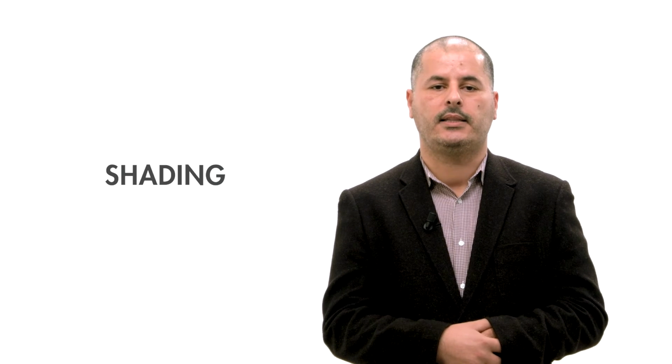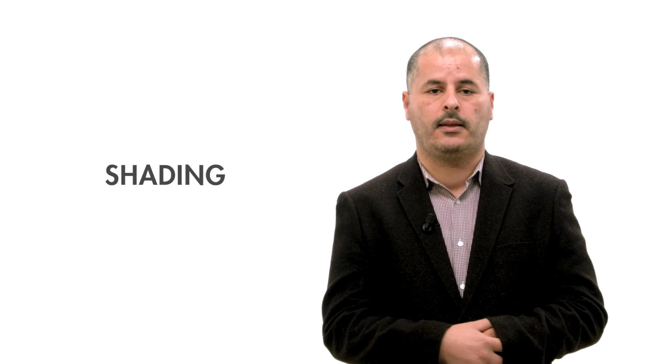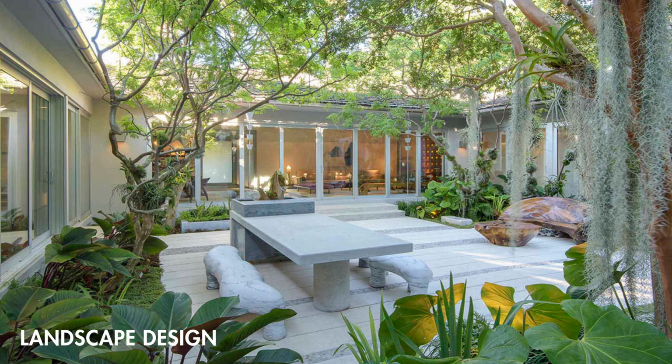Third technique is shading, where the solar heat gain creates uncomfortably high interior temperature. The most efficient way to protect a building from the solar radiation is by using different kinds of shading. Use shading elements or screens such as the traditional mashrabiyah. Fourth technique is landscape design that can provide shade for buildings and outdoor spaces. Trees and shrubs protect building parts from direct solar radiation.